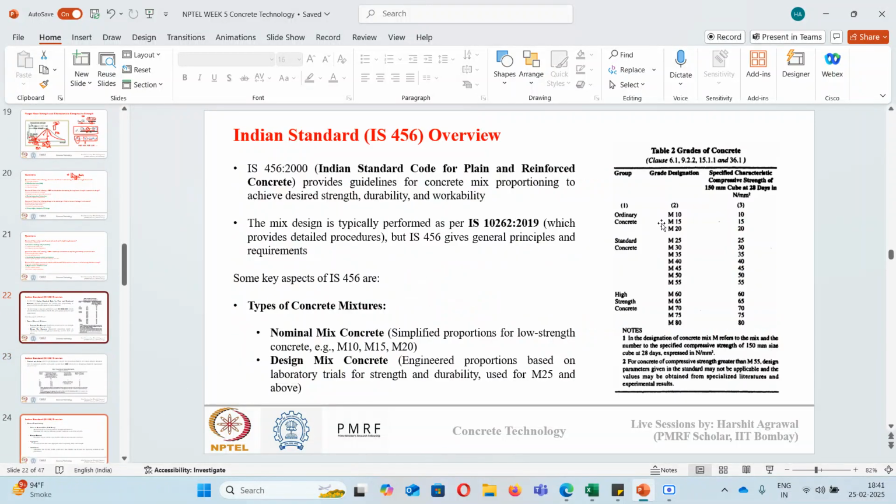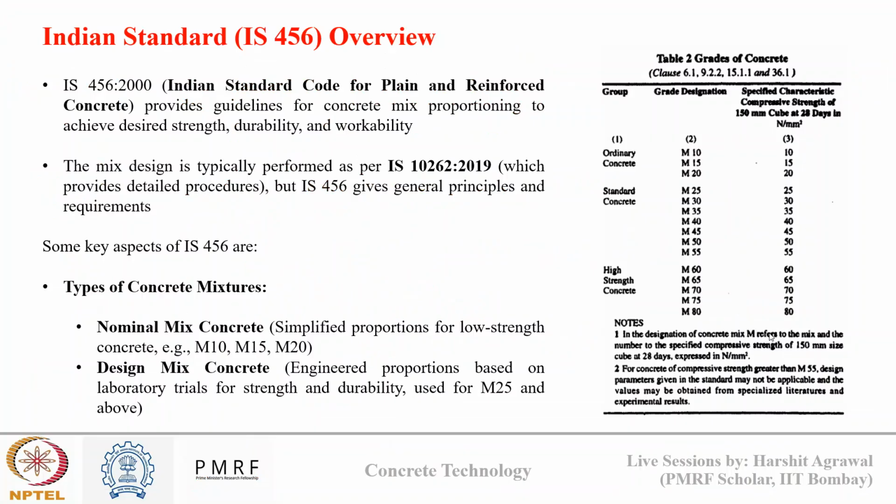Okay, so let's move ahead now. So now we will start with the discussion of mixture design as per Indian standard. Now here, though I will be covering the standards, it is more important for everyone to read the standards on their own also, line by line, because that is the best way to learn a codal provision. And these standards like IS 456, IS 10262, are freely available for download. So you can easily download them from Google and have a reading.